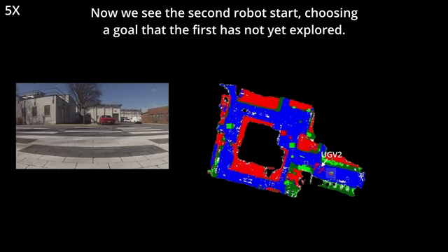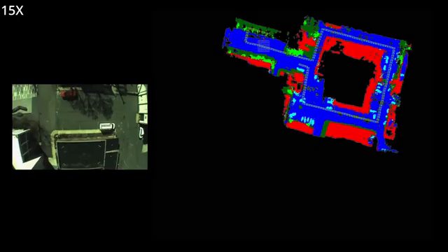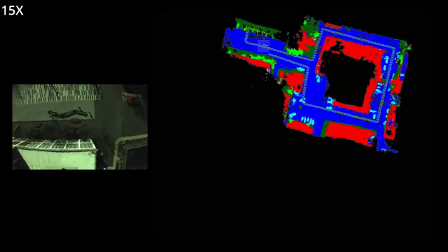We now see the perspective of the second UGV. It can tell that the first robot has claimed the closest goal region, so instead it navigates to another. All of this communication is performed on top of a Wi-Fi-based decentralized mesh network in a distributed database, where robots opportunistically synchronize their best understanding of the team state with other robots.